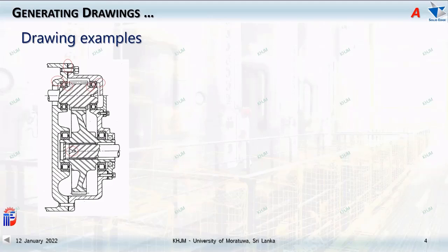And what is missing here? You can see this is the shaft that is supposed to go out of the end cap or the housing, you see over there. So in that case, you need to have a seal over here so that the oil or whatever liquid is inside will not squeeze out. Right? So that provision has to be there.